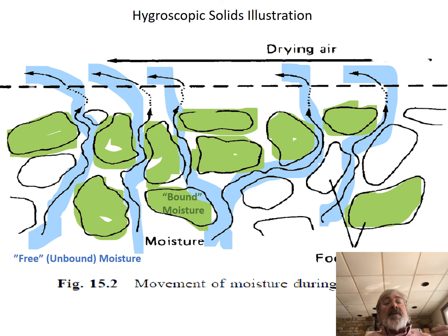So these different drying zones, to me, it's a lot easier if I visualize why these zones are there. If you can visualize that early on when the moisture content of your malt's super high, you've got moisture just hanging around, not really locked up in anything, basically free, unbound moisture, that will evaporate readily.